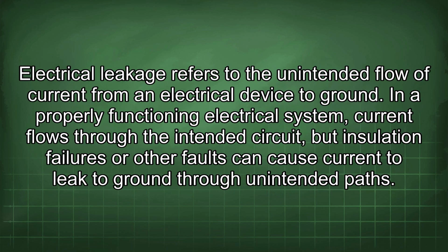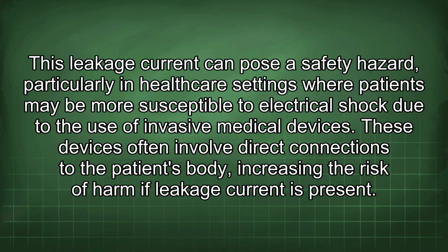Electrical leakage refers to the unintended flow of current from an electrical device to ground. In a properly functioning electrical system, current flows through the intended circuit, but insulation failures or other faults can cause current to leak to ground through unintended paths. This leakage current can pose a safety hazard, particularly in healthcare settings where patients may be more susceptible to electrical shock due to the use of invasive medical devices.